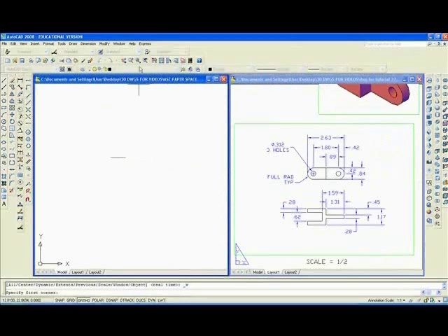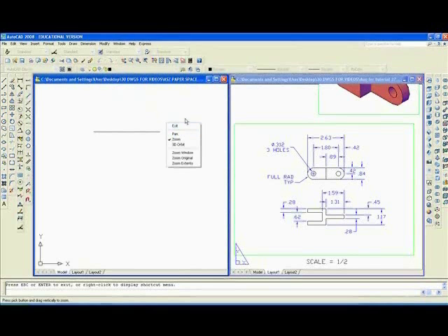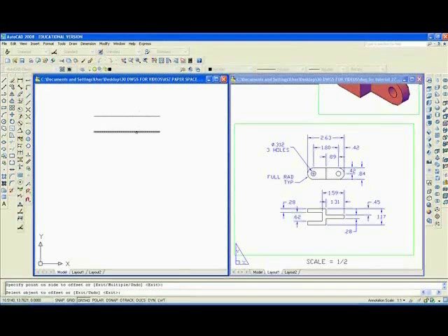And I'm going to zoom it, try to center it a little bit. Might even zoom it some more. And now I want to offset. O, enter. O, enter. 0.42, enter. Then I'm going to F, enter. Fillet two parallel lines. Remember what happens. Get a full radius.